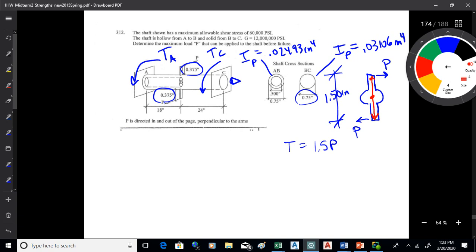So you got half of the offset on either side. When you add the two together, you just get the offset times the load. So you get 0.75P plus 0.75P. They're actually negative as I have it drawn there, but let's not worry about the signs so much. The magnitude of that is 1.5 times P. So you good with that?